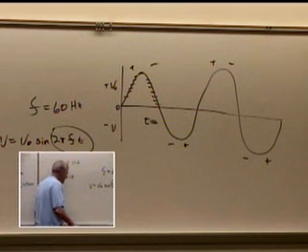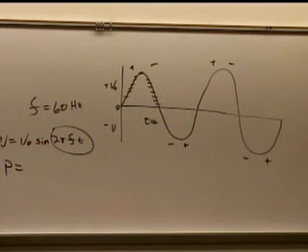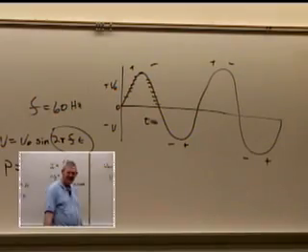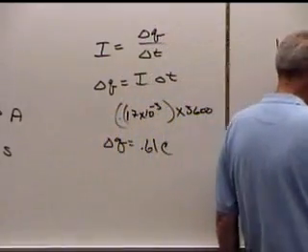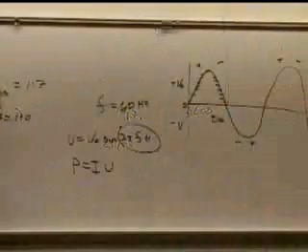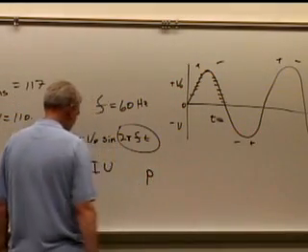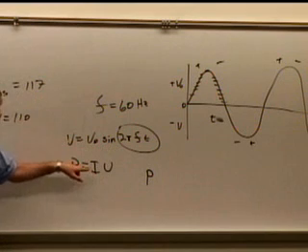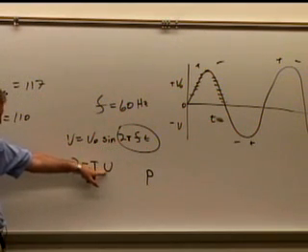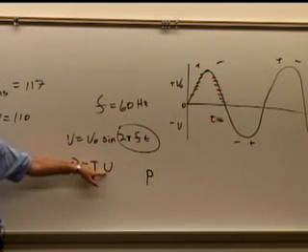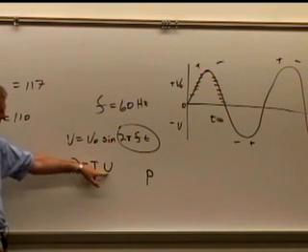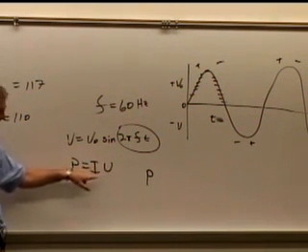And so we get this. So the average power, what did we say power was? What's the equation? Y'all learned it 25 minutes ago? You should have it. Yes, power equals IV. You should have it memorized. Now, as John was saying, since we got this VRMS, we're going to talk about the average power. Since power equals IV, notice what's happening here with V. It's going between positive and negative. But when the voltage is negative, guess what? So is the amperage.